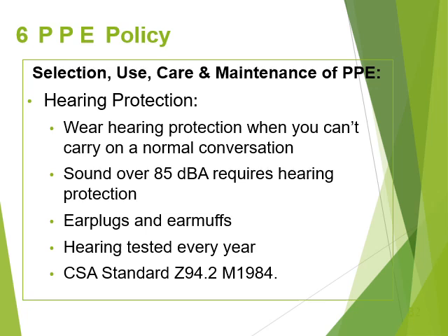The most common types of hearing protection used in construction are earplugs and earmuffs. Different styles of hearing protection need to be available at the sites, as different people have different head and ear sizes and types. Earplugs should be rolled in your fingers prior to insertion, softening them and ensuring a good fit. Earmuffs need to be sealed tightly around the ears.